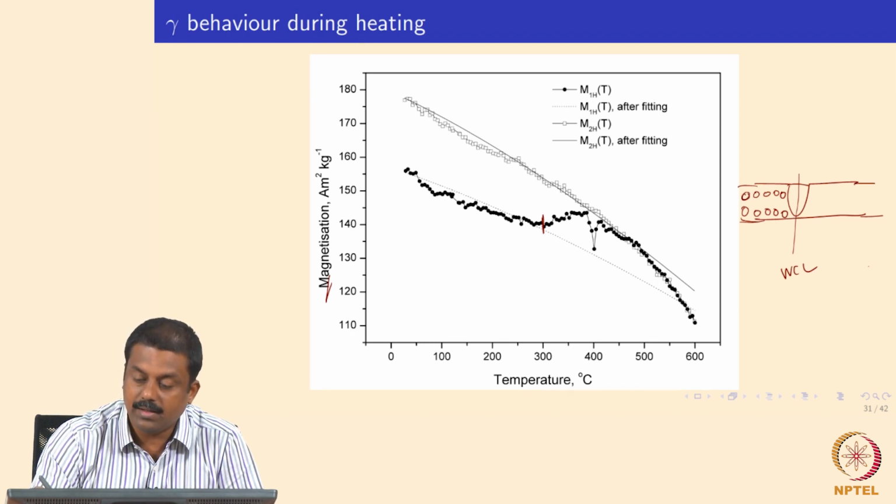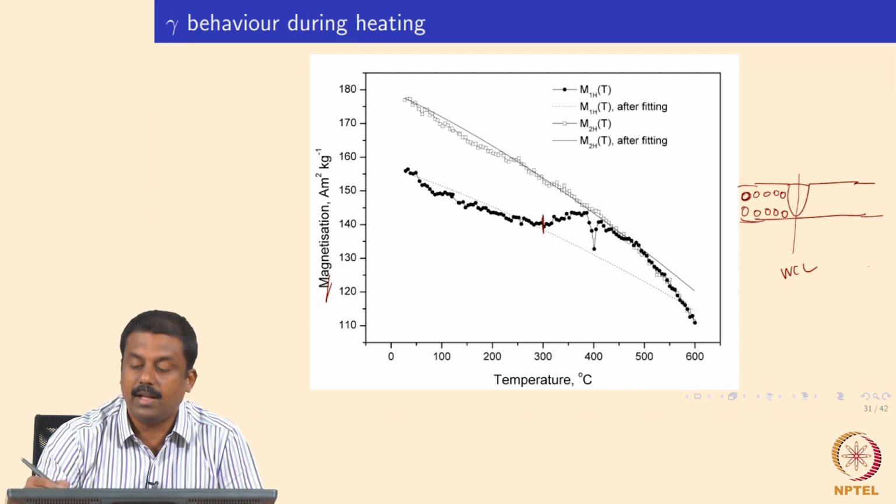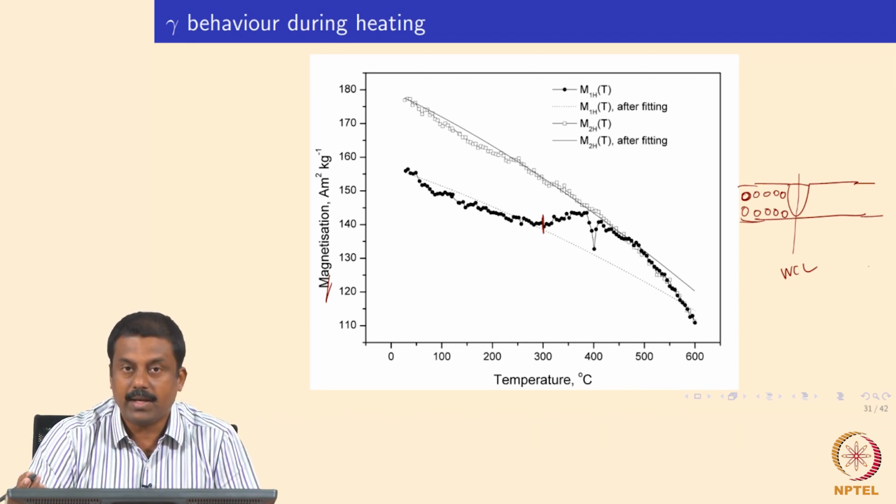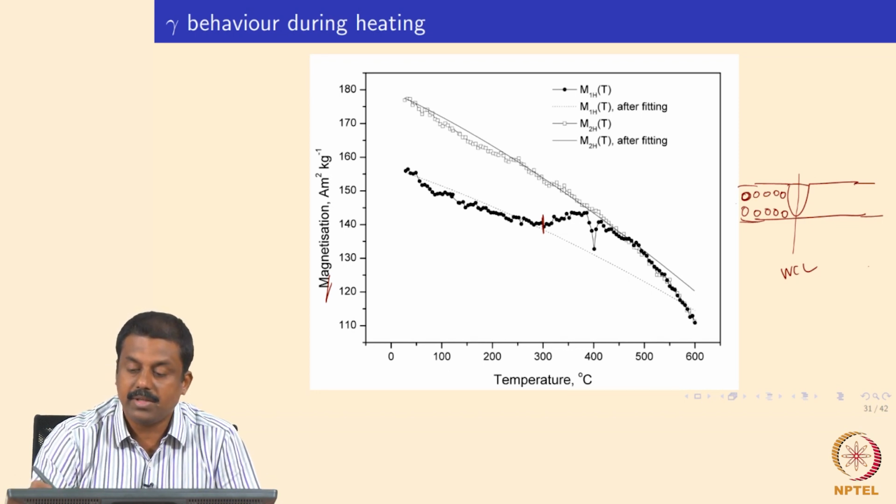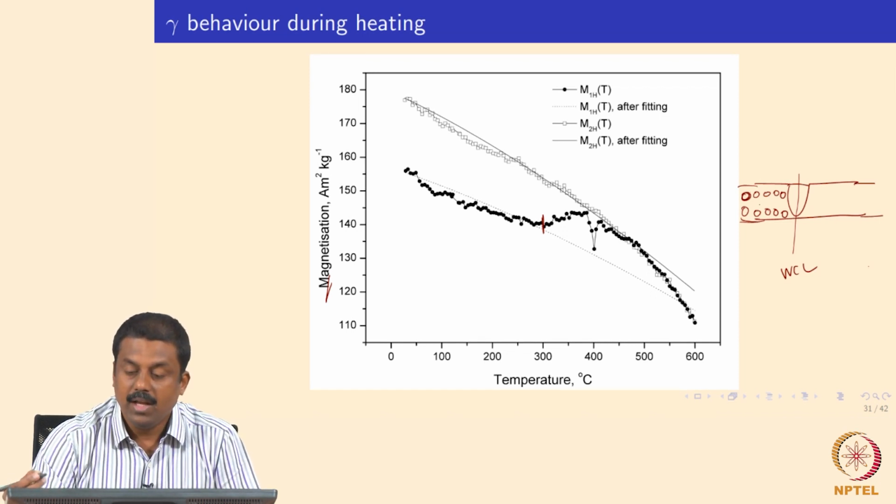Not like, for example, optical microscopy, where you look at retained austenite fraction in very local regions. You are not measuring what is below the surface, just the surface. Whereas in the magnetic saturation method, you are measuring throughout the sample in a bulk measurement. So that is an advantage, but the disadvantage is you need to measure over wide regions.